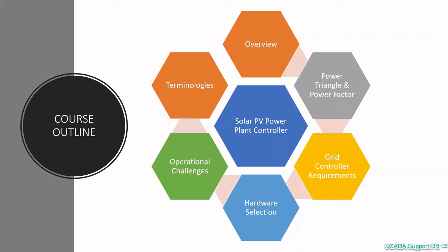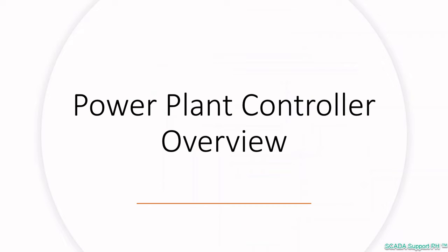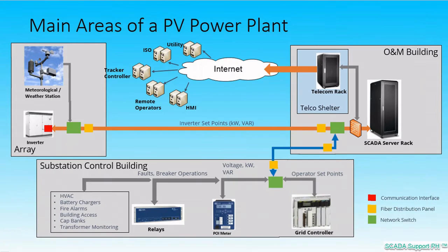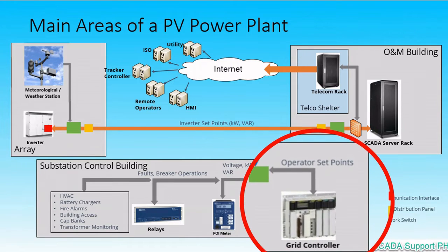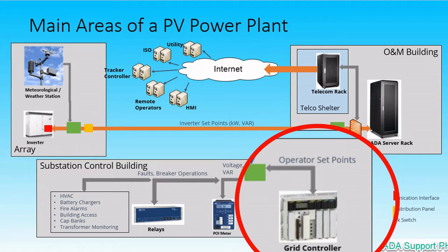We'll also tackle PPC hardware selection criteria and recognize those challenges being faced by PV power plant owners or grid operators while working with PPCs, and some common acronyms and terminologies at the very end. From our previous discussion on the areas of the solar PV power plant, within this specific example, the grid controller is centrally located on the substation control building.